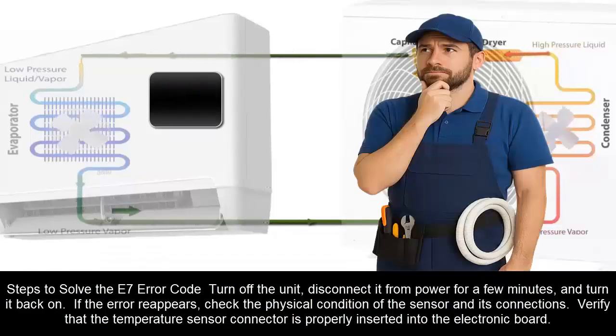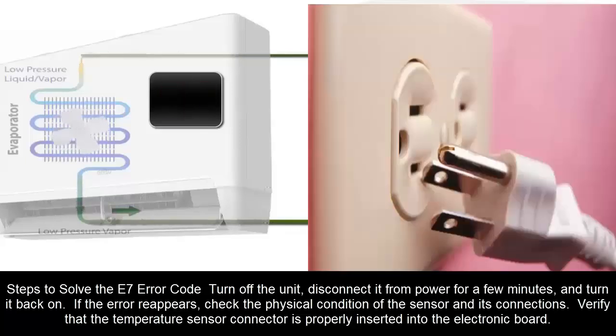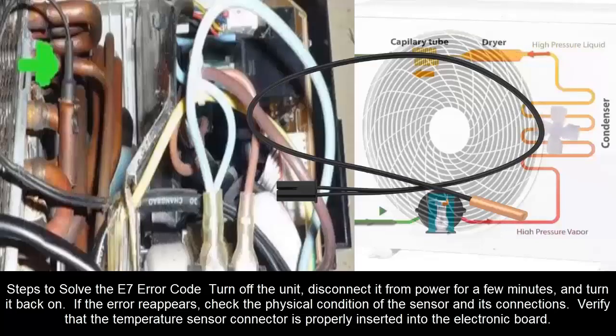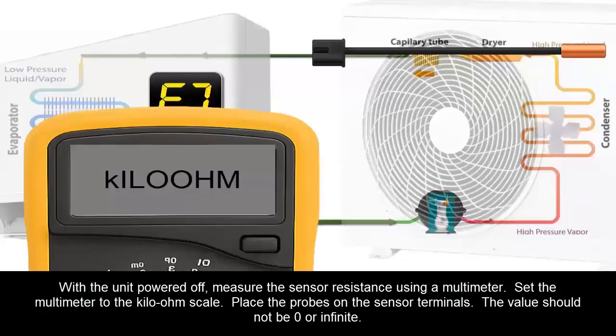Steps to solve the E7 error code. Turn off the unit, disconnect it from power for a few minutes, and turn it back on. If the error reappears, check the physical condition of the sensor and its connections. Verify that the temperature sensor connector is properly inserted into the electronic board. With the unit powered off, measure the resistance values of the sensor using a multimeter.